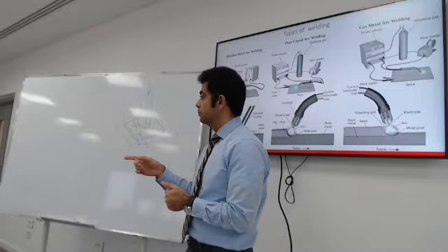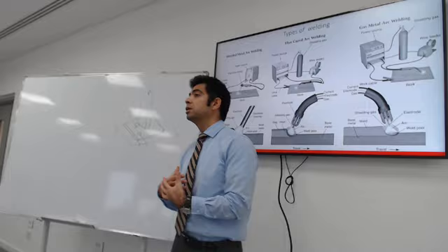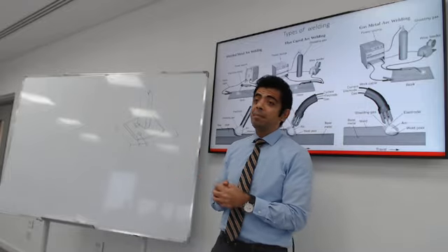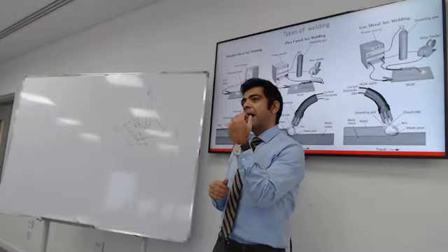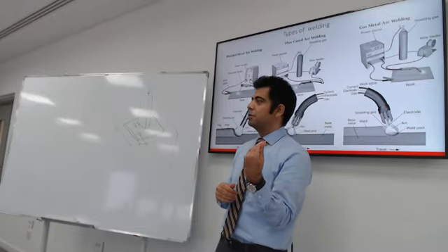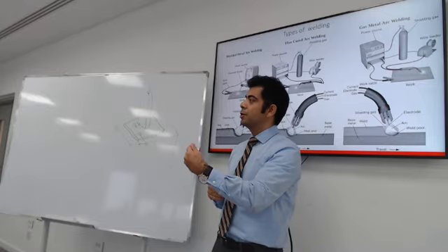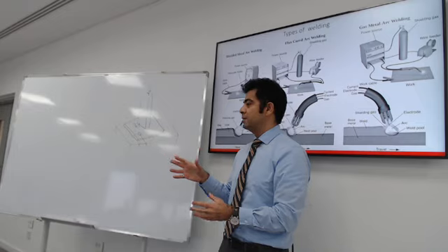Yes, that's true. So this is the reason why I wouldn't be super excited about a field weld connection. I would rather have the weld in the fabrication shop and then any connections on site to be bolted, for these exact reasons.